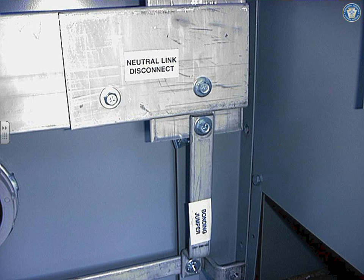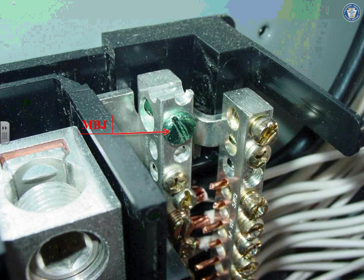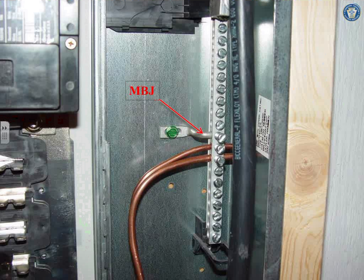What I like about these is the pictures, because they're much better than my pictures. Same thing, main bonding jumper. The idea is to bond your neutral to the enclosure where the disconnect is residing, as well as to the grounding electrode system right inside the service panel. Here's your main bonding jumper. This is my neutral bar bonded to the grounding electrode system and bonded to the enclosure.